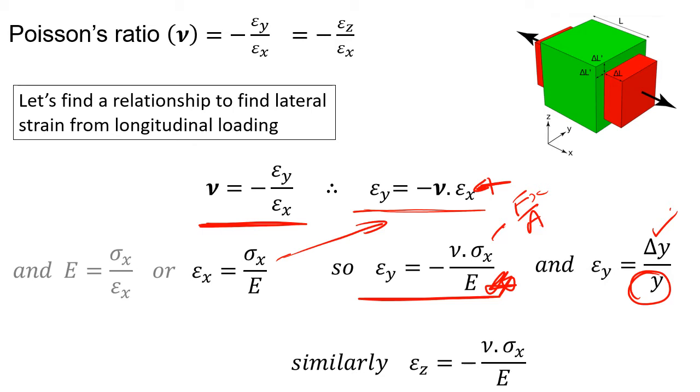If we've got maybe a shaft with a collar clamped around it, and we put an axial load on that, so if we put a tensile load on it, the diameter will get less, and that collar that's clamped around it may actually come loose. So it's important that we can calculate out what this relationship will give us effectively.